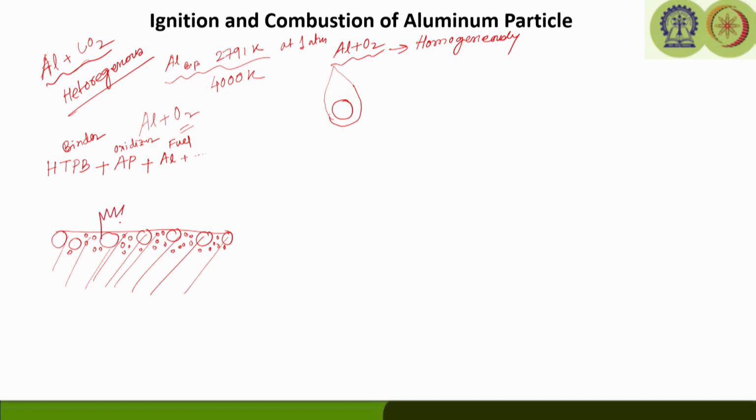As you recall, for a composite propellant there is a triple flame structure. Initially, it will have an ammonium perchlorate premixed flame. The HTPB binder is going to pyrolyze and vaporize, producing fuel vapor that is going to mix with the oxidizing vapor, and they will create a primary diffusion flame. So, this is your APPF, which is going to create the primary diffusion flame.